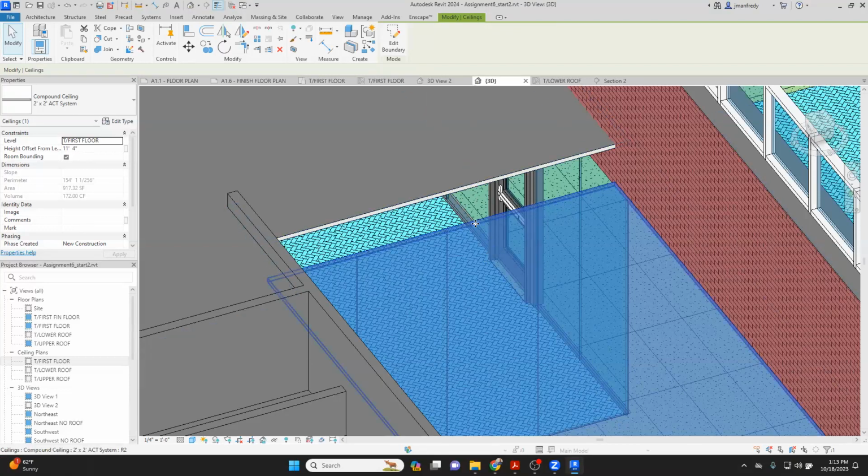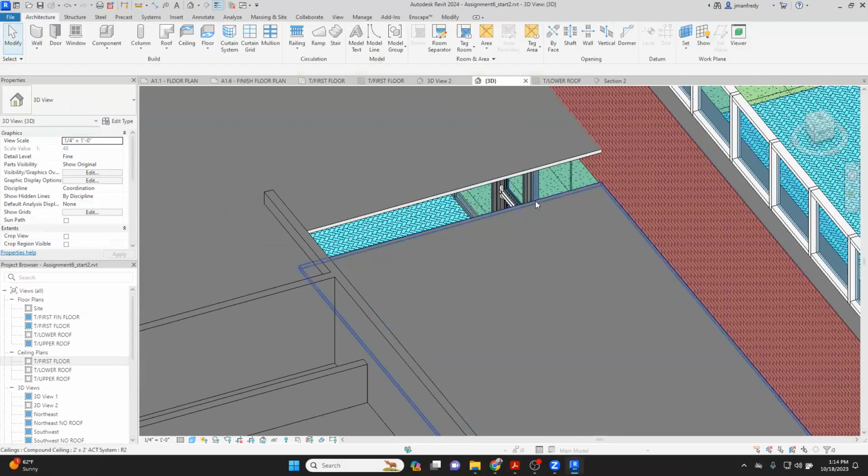The wall that you want to put there is called a soffit. Because if you put a normal wall in there, it's going to be a waste of money, right? A normal gypboard wall has gypboard on both sides of a metal stud. You only want gypboard on one side, the side you're going to paint from inside this room. The back side, we don't really care what it looks like because it's above the ceiling. No one's going to see it. We don't want to pay for gypboard up there.